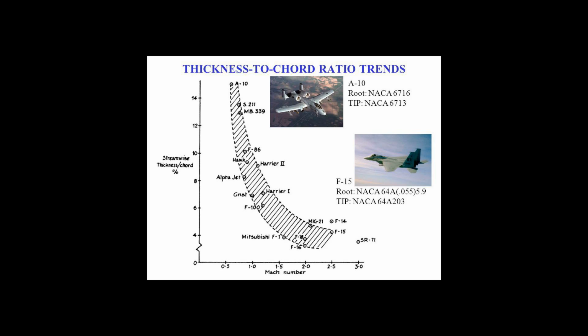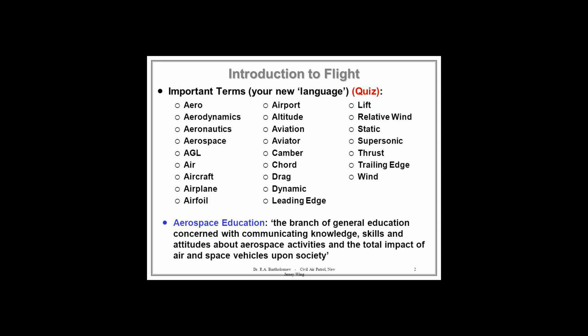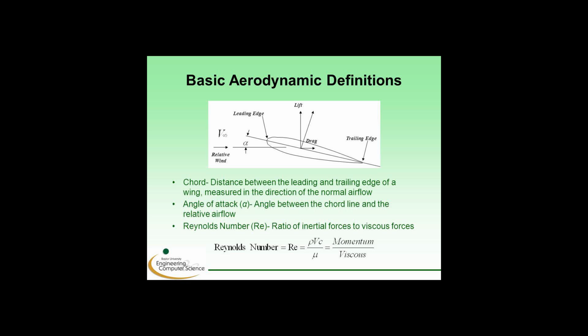Mean aerodynamic chord. Mean aerodynamic chord, MAC, is defined as MAC = (2/S) ∫ from 0 to b/2 of c² dy, where y is the coordinate along the wingspan and c is the chord at the coordinate y. Other terms are as for SMC.